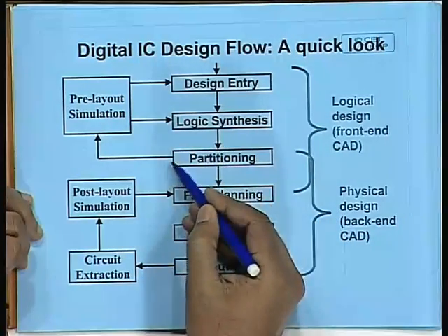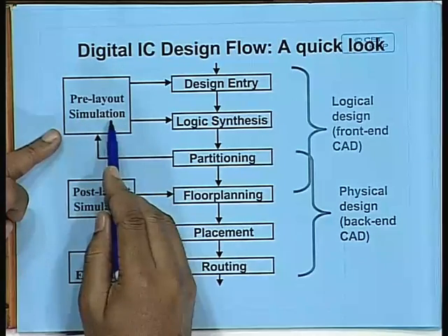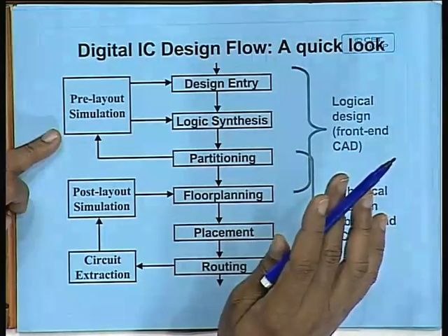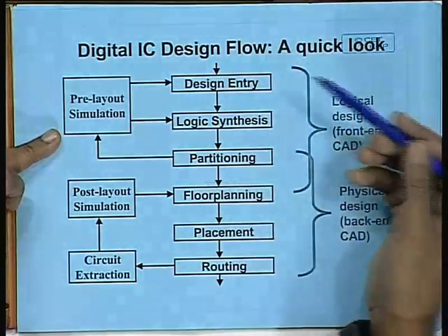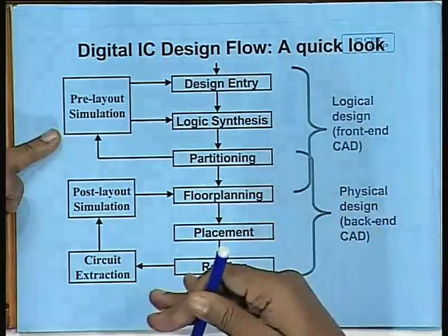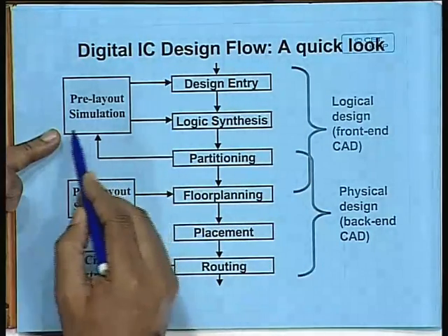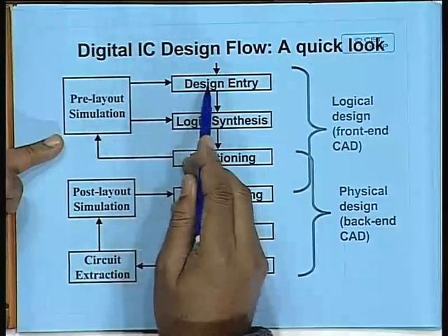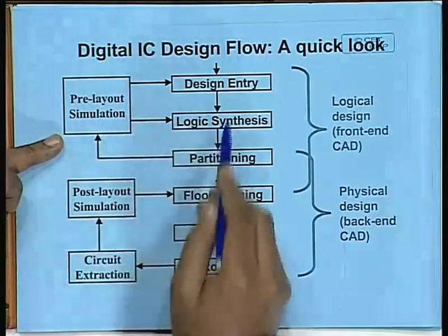Typically either after partitioning or before partitioning, you do something called pre-layout simulation to verify whether your behavior or the process of synthesis was correct or is there anything wrong. Now you will see that if you specify a design in Verilog, there are some features which are perfectly okay when you specify it, but during synthesis it will give error, it cannot be synthesized. These are the things we will be discussing later. So you carry out a pre-layout simulation, and if you get any errors or inconsistency, you can modify either your original design specification or you can make some changes at the logic synthesis level also in order to rectify that defect.